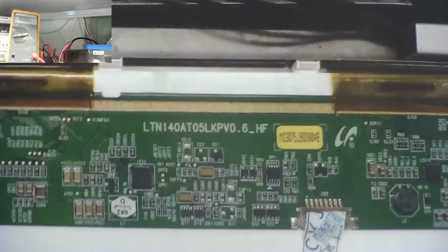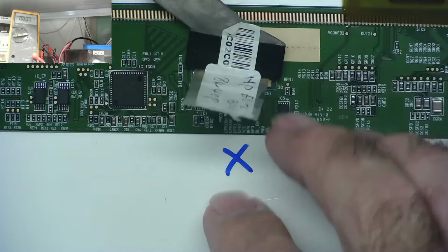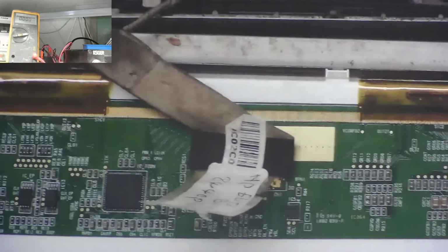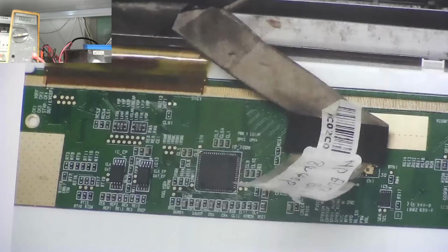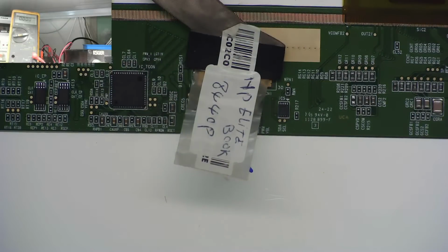Then we can put the other screen on. This, by the way, is the one which has the picture, so I'm effectively measuring off a good one, even though we know the screen itself's faulty. I'll write all the voltages on here, then we'll put the video back on with the other one, and we'll compare with this one and see if we can see any difference between the two. See you in a few minutes.